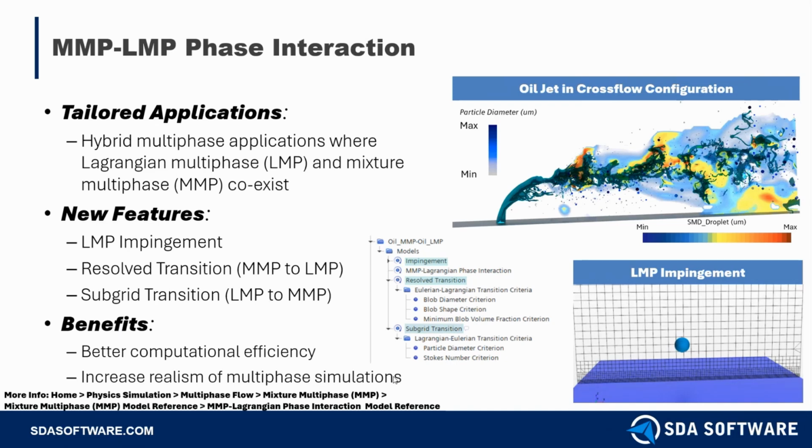Previously, hybrid multi-phase applications with a free surface were usually modeled using the volume of fluid method, the VOF method. The VOF method is generally a little bit more expensive for resolving the free surfaces compared to using the mixture multi-phase with a large-scale interface approach, short for the MMP-LSI approach. The MMP-LSI approach is a cheaper alternative for resolving the free surfaces, but the MMP to LMP phase interaction was kind of lacking in the previous version.